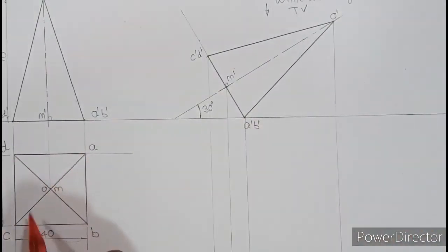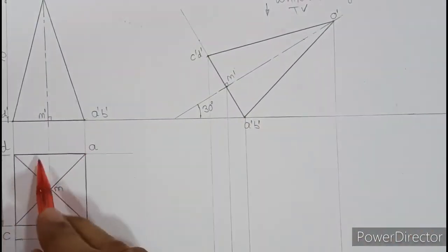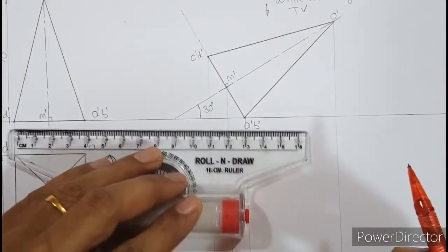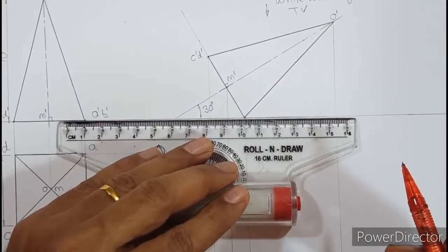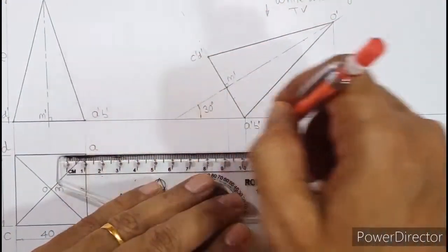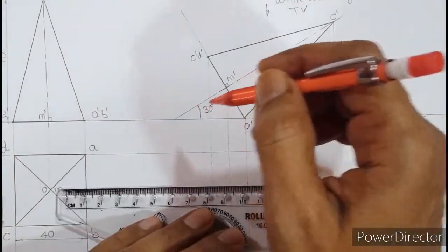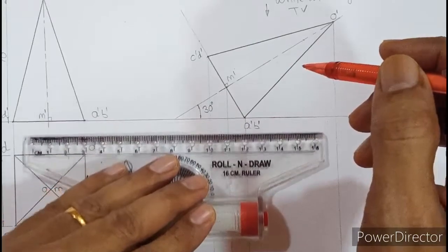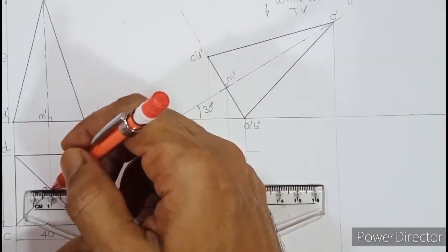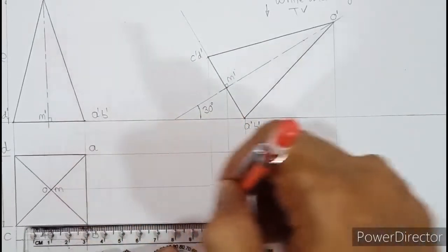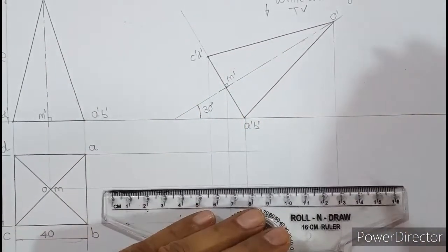Now if you look at this square, points A, B, C, D, O, M, you need to project on in the fourth diagram. So align the roller scale with this XY line, roll down, project A and D, they are in the same line. OM, so I need to go a little bit inside. Okay, so OM is also projected, and finally C to B, that is also done. I'll extend OM slightly beyond this.